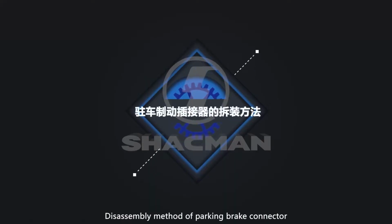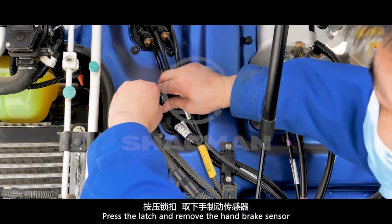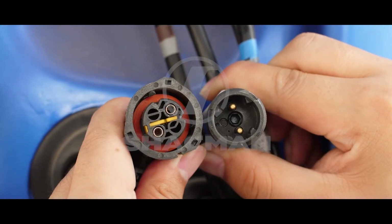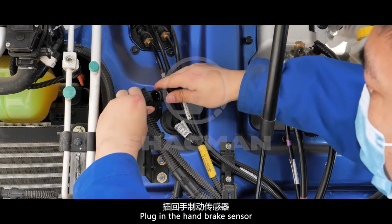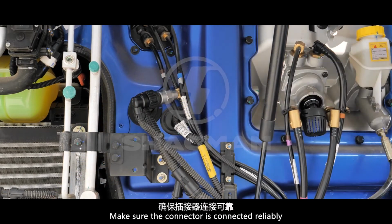Disassembly method of parking brake connector. Hand brake sensor. Press the latch and remove the hand brake sensor. Note: the parking brake sensor connector is equipped with error-proof design. Please pay attention when plugging in and out. Plug in the hand brake sensor. Make sure the connector is connected reliably.